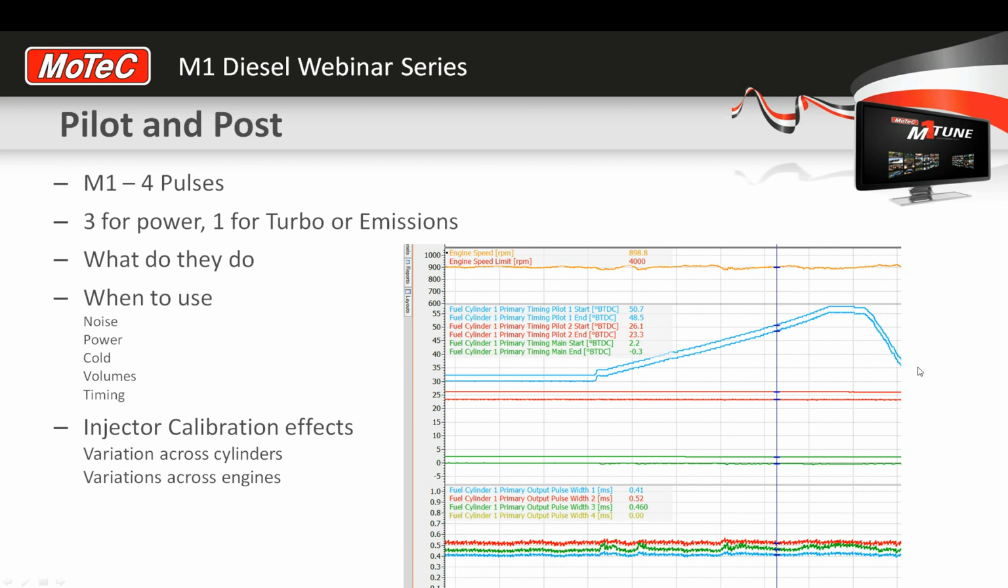If we're getting down to very, very small pilot pulses and very small pulse widths, then we can get scenarios where the engine thinks it's delivering fuel and potentially isn't on some injectors. So you get very minor drivability issues, associated with the fact that we don't know very accurately the flow of each injector in every cylinder.